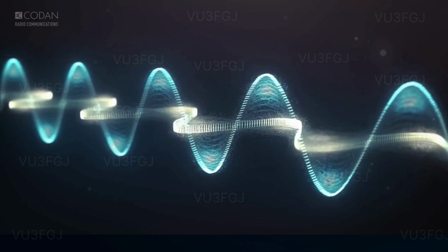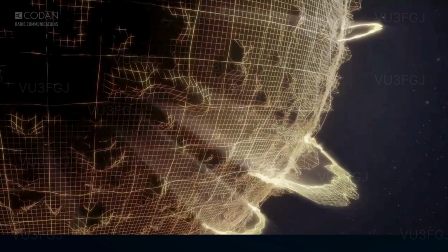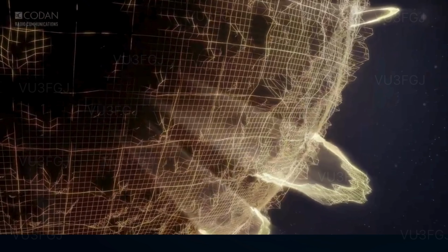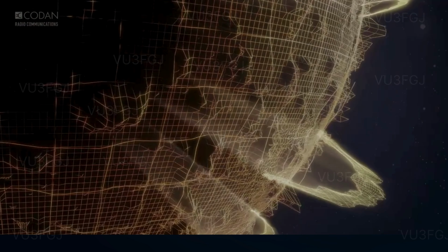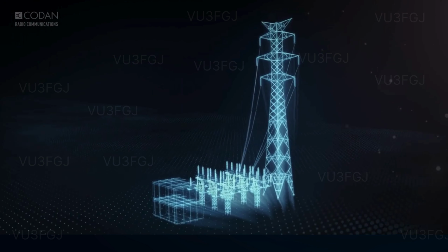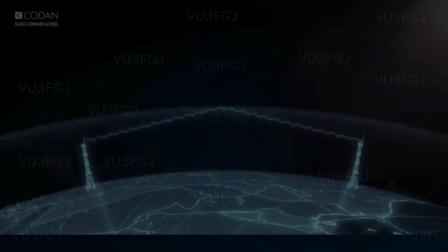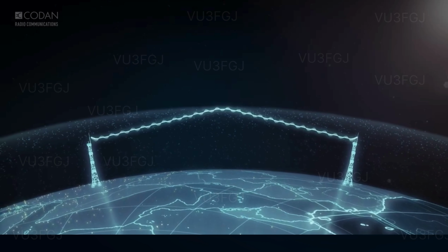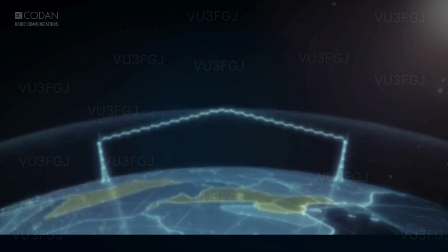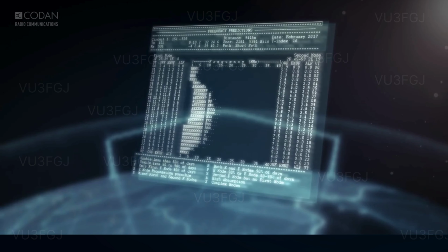What are some of the other factors that can affect HF radio waves? Solar flares can alter the refracting property of the ionosphere. 11-year solar cycles can either hinder or improve the HF radio waves. And finally, something man-made, such as power stations which produce electrical noise, can affect the reception of HF signals. Apart from these factors, communication through HF radio waves depends on a few other things, like location, local radio rules and regulations, planning for the frequency sets to be used.